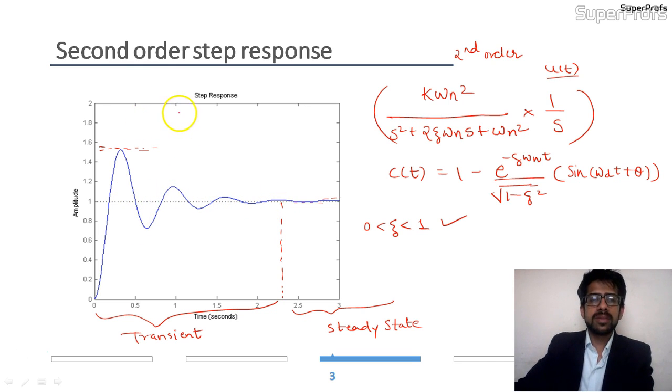Now, a human might desire more oscillations but lesser overshoot. Sometimes a user requires more overshoot but less pulses before they die out. So, for a system design of a second order system, it is very much required to model the system according to user needs, and to know that we must understand what are the typical parameters which are governed to describe the transient response of a system.